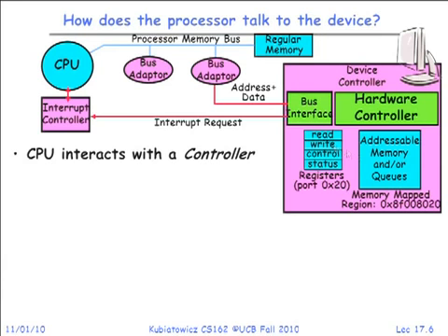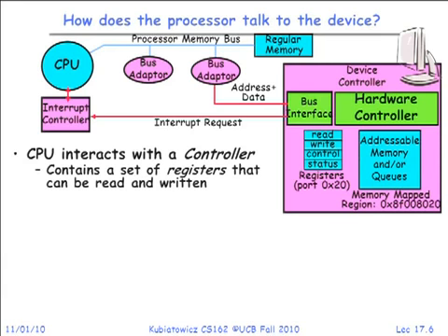So the question is, how does the processor talk to that? Does anybody know? How does the processor actually access a device? Or maybe the right question is, what does a device driver have to do? Load or store word to a particular address that maps to these interfaces. Good. So one thought is we somehow map addresses here onto our physical memory addresses such that the CPU can read and write them. What else could they do?